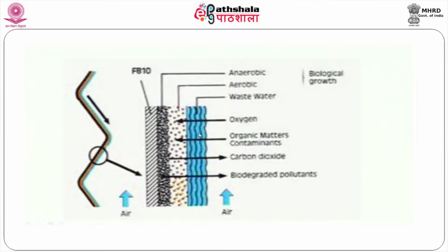So, in order to maintain aerobic activity, we have to provide adequate DO. So, oxygen present in the pore space will diffuse into the biological layer. If we investigate the pore space with respect to atmospheric air, a partial pressure gradient is established. That is why continuous mass transfer will occur because of the partial pressure gradient between the pore space and atmospheric air.